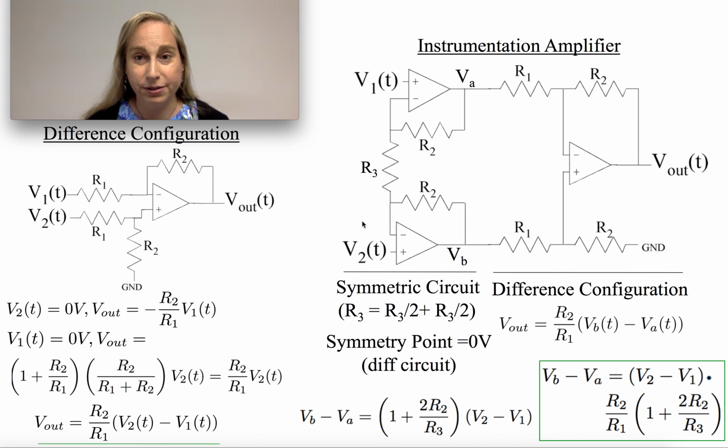One is a straightforward difference amplifier configuration that you see below. It's basically a very simple setup: I have two inputs, V1 and V2, and an output of V out. Interesting circuit. If I think about this from a simple superposition perspective, what am I going to see? If I let V2 be 0, basically just grounding this voltage, I notice that I have an inverting amplifier, and I know precisely what that solution looks like in terms of V1. Great. Let me take a different case. Let me assume that V1 is now equal to 0. What circuit would I now see?